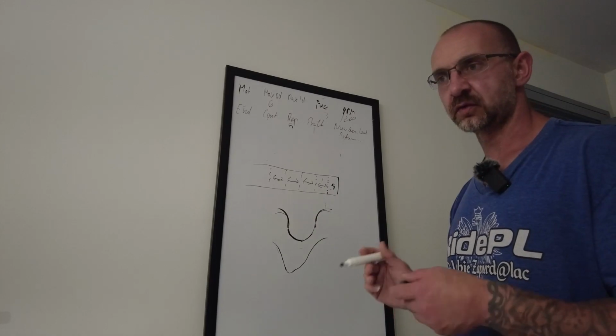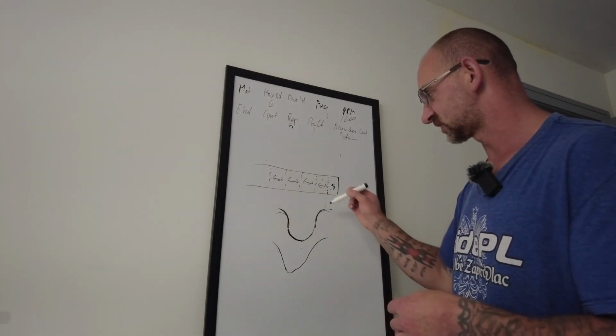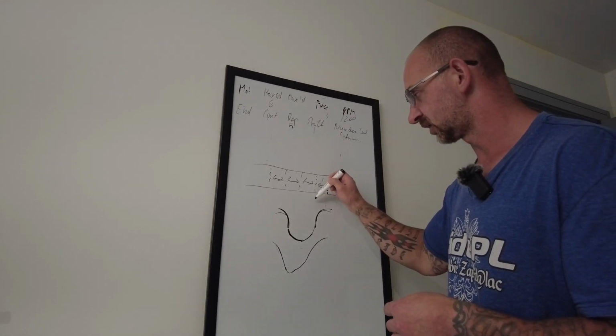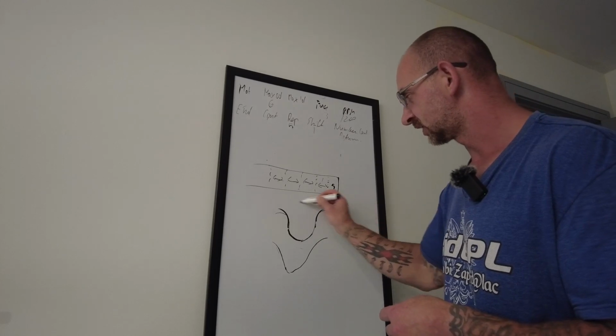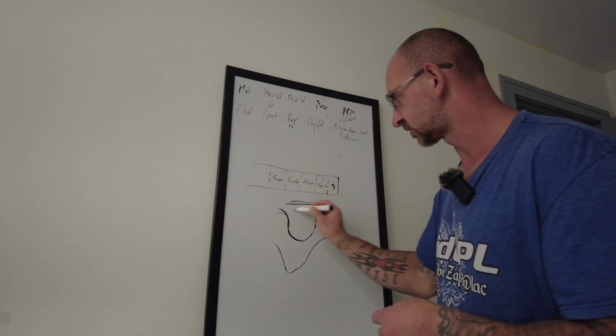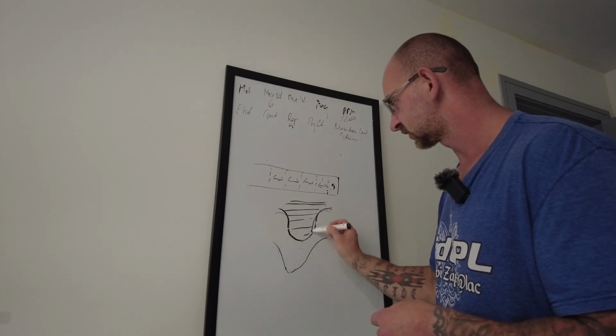Then I take a grooving tool, I set it as a general tool, and I set my angles at 0. Setting the angles at 0 allows the Mazak to go down, and I just do it in this feature. Then the finish comes in and finishes that.